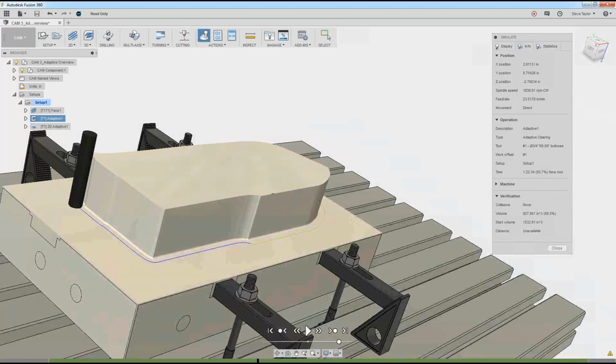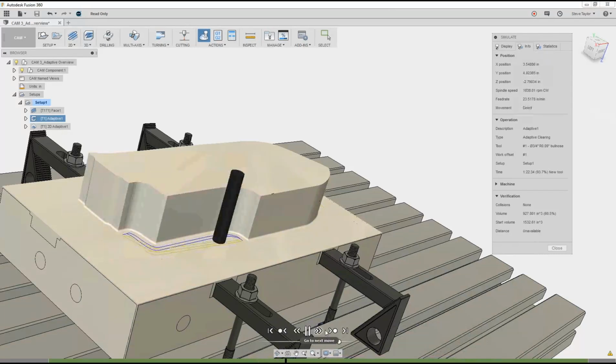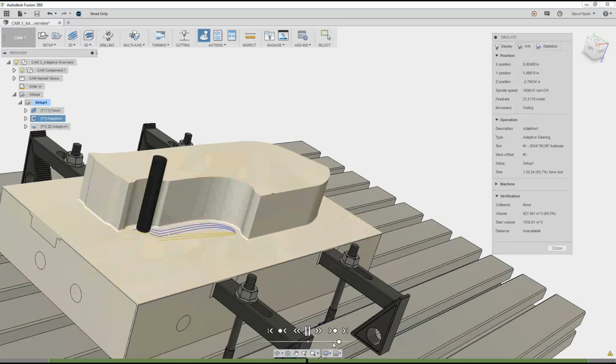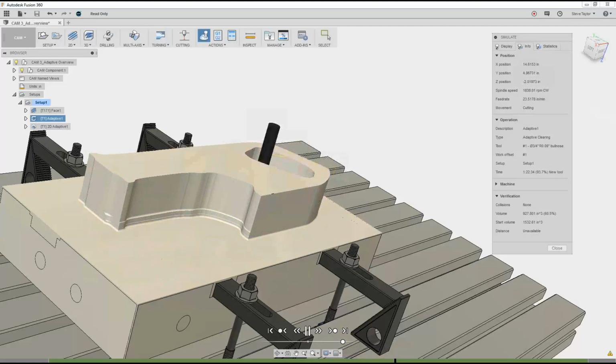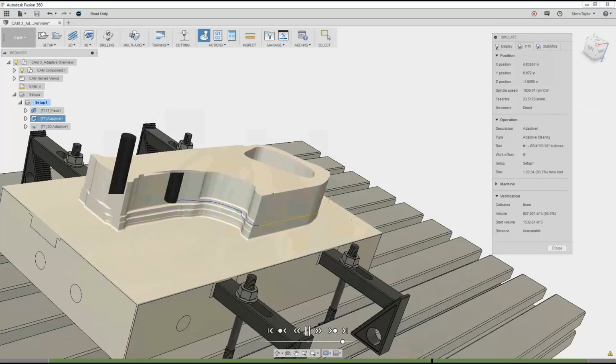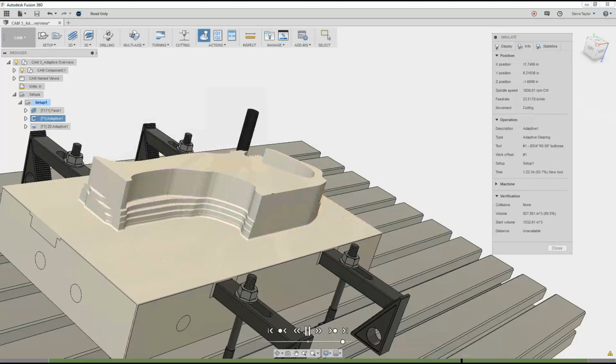And what we'll also see down at the bottom here is this green line. Now, if there is collisions or there is a problem, you'll notice later on there may be some red parts, which might be to do with the length of the tool that we're using. So I'll just let that go. We can move on to the next step. Speed it up even quicker. There we go, as it's going down. I say currently there's no collisions, so there's no red dashes in there. You can see the values changing, there's tool moves, different operations.